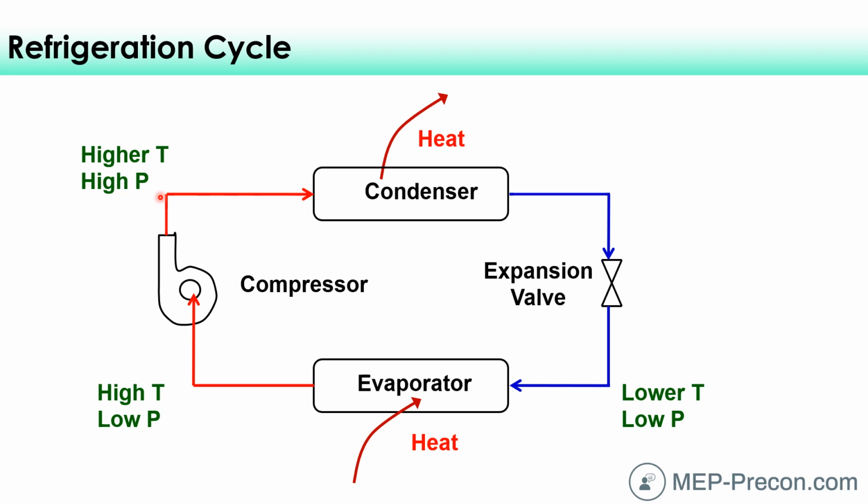That's kind of an important concept to understand, that we're not adding heat really with this compressor. Maybe a little bit of work on it, but it's the same amount of heat that we're absorbing. The BTU heat we've absorbed from the space, we're just changing the temperature of that by increasing the pressure through that perfect gas law. Okay, so the reason why we pump that up to a higher temperature is so that we can have heat transfer within our outdoor condenser coil.